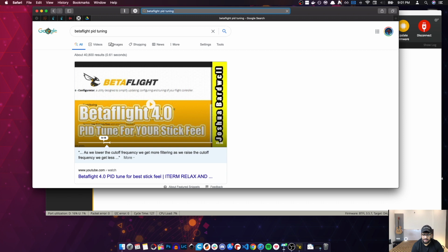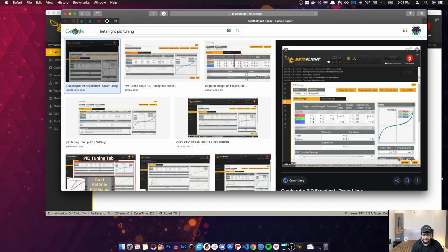So okay, that's what I wanted to show you. This is the PID tuning page on Betaflight, and you can see here it says proportional roll 50, proportional pitch 80, proportional yaw 90. These are the values of kp for each axis, and similarly for I and similarly for D. This is how you can change it, and this is how you can tune it. If you think that your kp is less for pitch, you can come back after the flight, increase it, save it, and you're good to go. So that is about firmwares and how you can use an open source firmware, flash your flight controller with it, and tune the parameters you want.